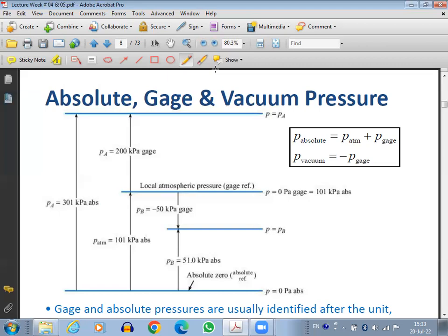That's why we have absolute temperature. Absolute temperature is the Kelvin temperature scale. Can it go negative? Can there be negative Kelvin? No, not possible. The minimum is 0 Kelvin. In the same way, based on the same concept, we have absolute pressure. So for absolute pressure, our reference point is absolute vacuum, zero pressure. From this reference point, we judge any pressure, whether the pressure is high, low, whatever it is. But our reference point is vacuum. So do you understand the concept of absolute pressure?